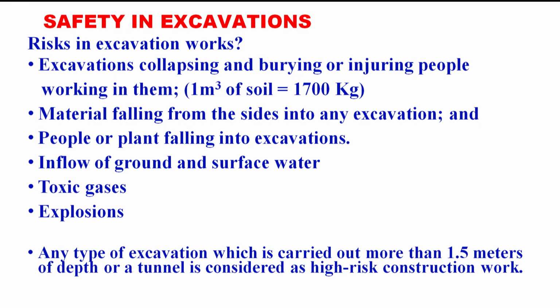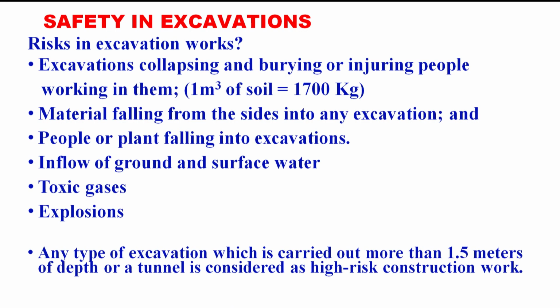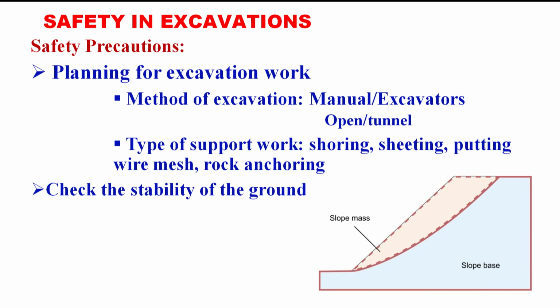Then any excavation carried out more than 1.5 meter of depth, or a tunnel, whether you are doing open excavation deeper than 1.5 meter or tunnel boring, is considered high risk construction work, and proper care should be taken while doing such work. In both cases, one has to be very careful.